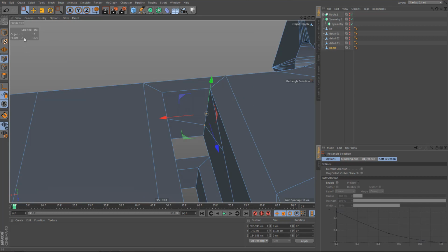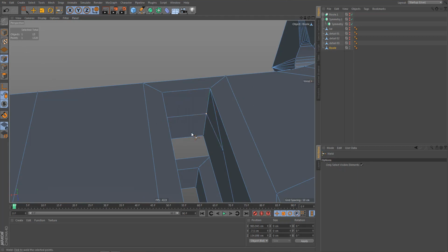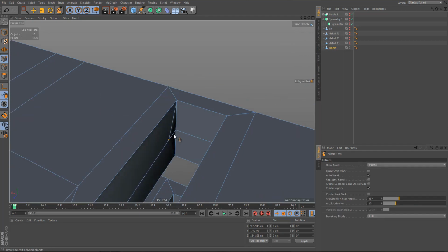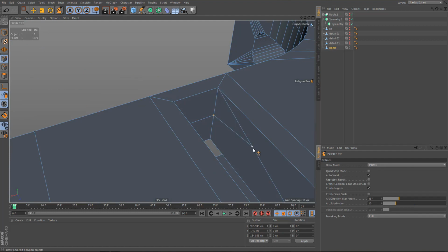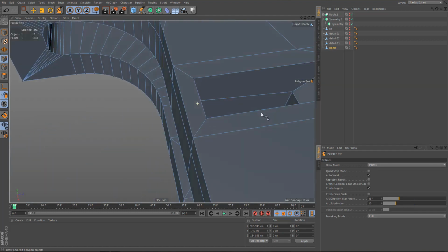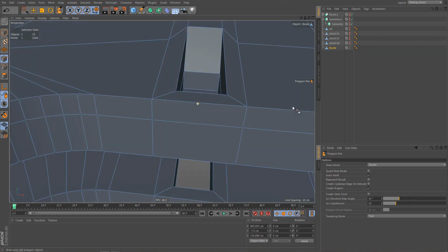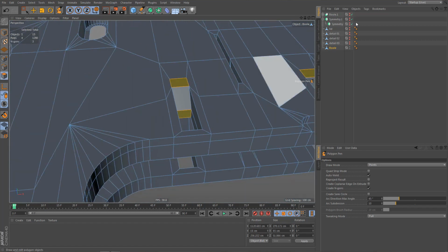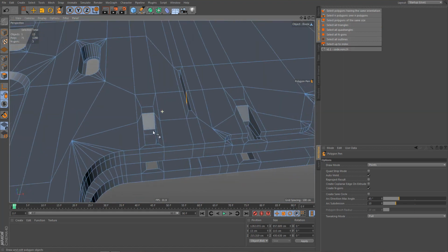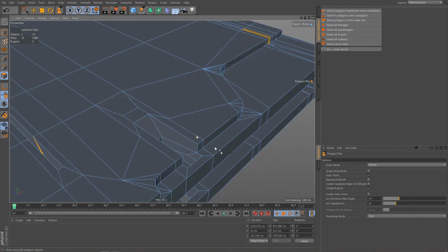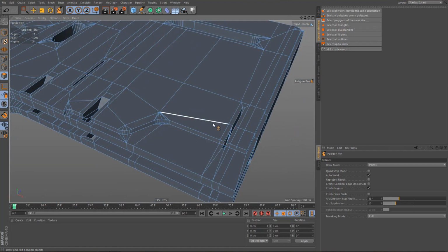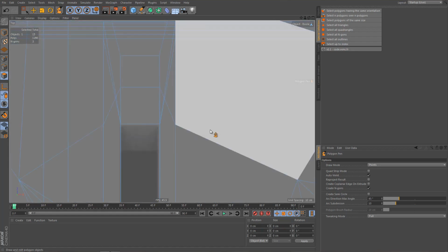Make sure that I only have 2 points selected, and I'm going to weld them up to this point. And then we should hopefully be able to weld these. Okay, and this time I didn't screw up this area here. So we've got quads here. Let's just check that by selecting all triangles. Okay, and this time I did everything right.